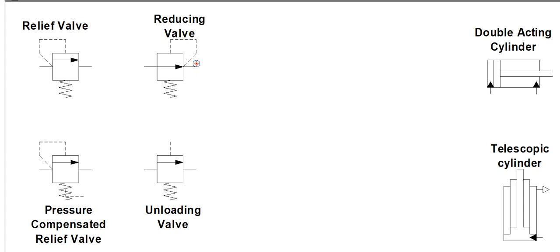So this valve always maintains 1000 psi on its outlet. You would see this valve used a lot in transmission circuits, such as power shift transmissions. Power shift transmissions need roughly 300 to 400 psi of oil pressure at all times. If you have a pump whose pressure ranges anywhere from 500 up to 3000, you don't want your transmission clutch pressures to change. So you would use a pressure reducing valve set to, say, 300. Anytime the inlet pressure fluctuates or tries to go above 300, this valve will self-regulate and always maintain 300 on the outlet of the valve.